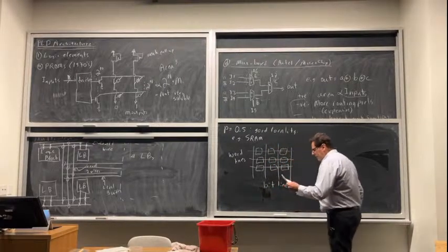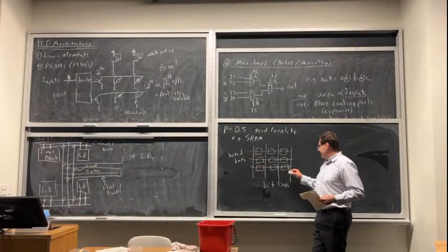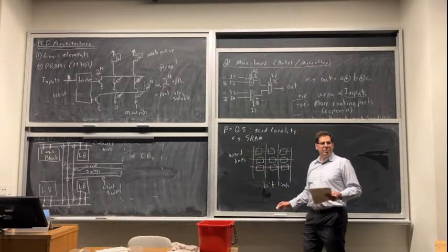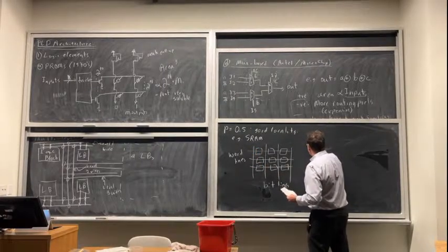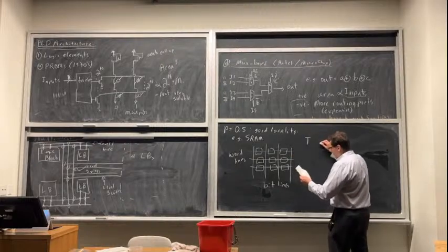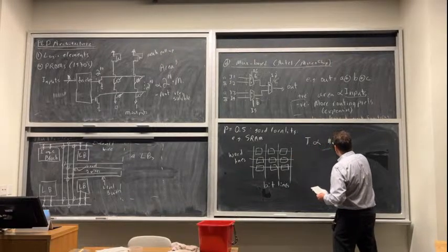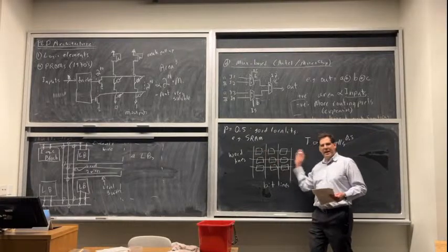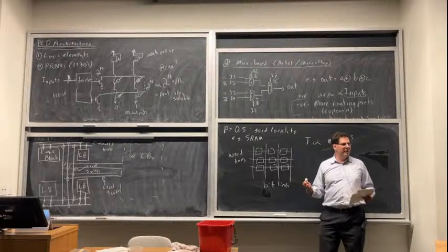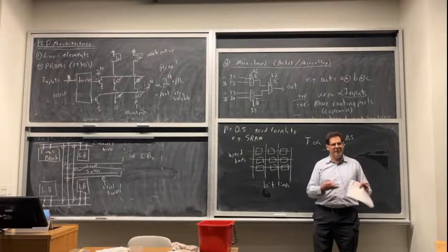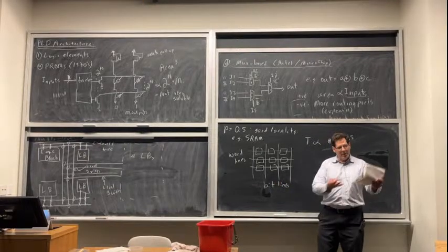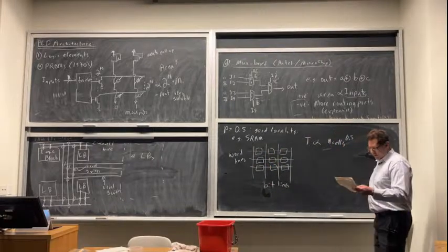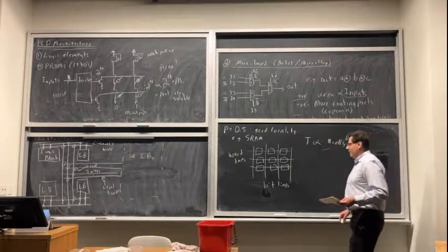If I take the area, like the number of SRAM cells, the amount of stuff inside of here is basically word lines times bit lines. So phrased another way, the number of terminals is therefore proportional to the number of SRAM cells to the 0.5. It kind of makes sense. Basically, I've got an area, and all the input and output is on the perimeter. So it's kind of like, what is the relationship between the perimeter and area of a square? The same thing would be true for essentially any kind of two-dimensional processing array, like a network switch too. So this is pretty good locality.